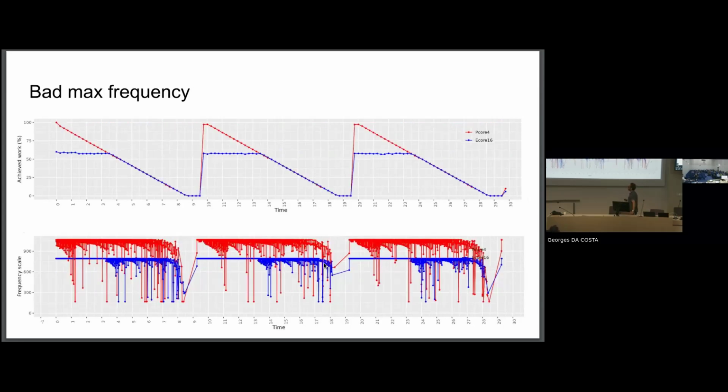And here is the reason. Again, in our work example, we see that the frequency scaling factor is correct for the P core. Well, not exactly correct, but more on that in a minute. However, on the E core, if we had correct frequency scaling, the blue line should also be on the 1024 limit when we run at max capacity. However, we see that it is maybe on 800. So we are underestimating the frequency scaling of the E cores.